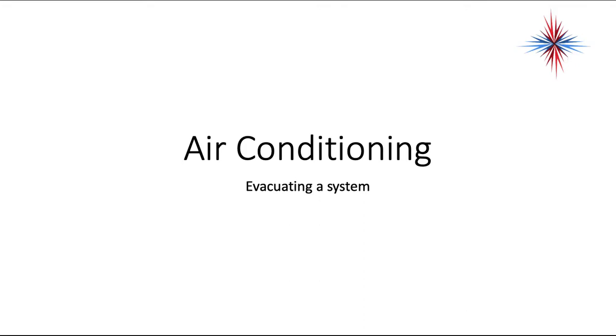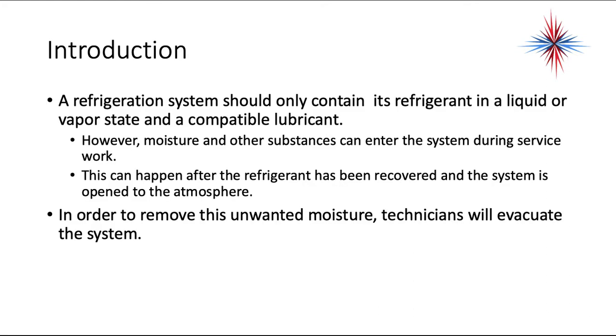In this video, we're going to be talking about evacuation, or putting a system into a vacuum after performing repair work and before you recharge it. A refrigeration system, and again, refrigeration system could be refrigeration or air conditioning. It's still a refrigeration system. Should only contain refrigerant in a liquid or vapor state and a compatible lubricant.